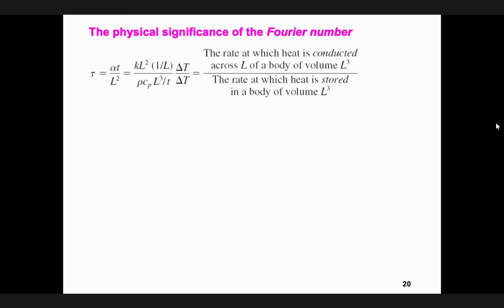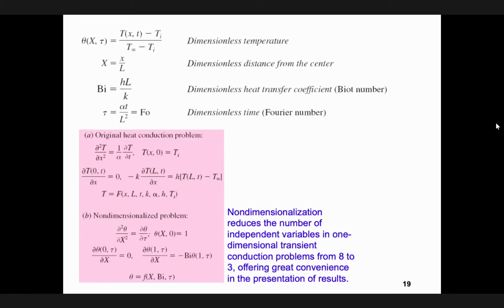And if you look at the physical meaning, again, we have to go back. As I mentioned, we look at the Reynolds number. The Reynolds number was representing 2 forces, inertial force and viscous force. Therefore, there are 2 effects. Fluid wants to go through the pipe, but viscosity was resisting. We have the Biot number, again, a ratio of 2 effects. You have convection and you have conduction. Therefore, it's trying to compare which one is dominating the system.